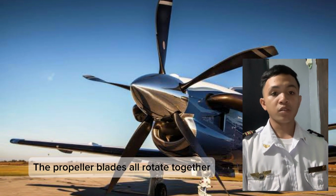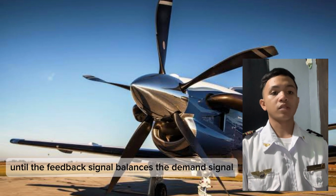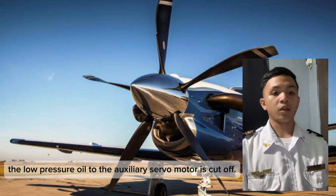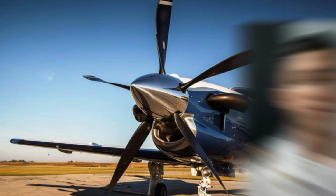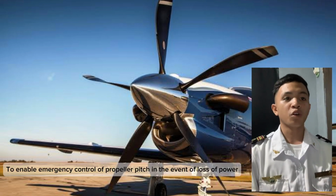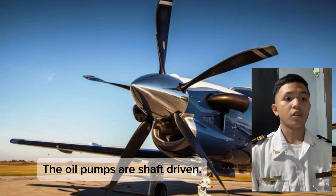The propeller blades all rotate together until the feedback signal balances the demand signal and the low-pressure oil to the auxiliary servo motor is cut off. To enable emergency control of propeller pitch in the event of loss of power, the spool valves can be operated by hand. The oil pumps are shaft driven.